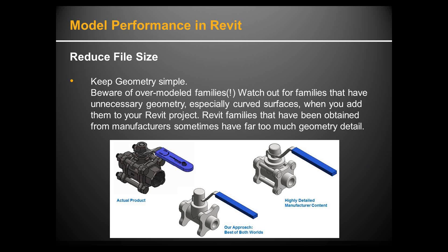Another thing we looked at, we had a bakery center they put in there, and no one ever looked inside what was in the bakery center. There happened to be cupcakes and bread and all this other stuff that someone had modeled in there, so far as to put the cupcake ridges on the wrappers. And you couldn't even see that. No, you couldn't ever see it because it wasn't a glass that was transparent. So getting used to that. Really take the time to look at what you're bringing in and edit that before you put it in the model.